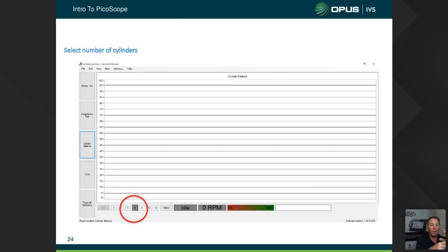And then we can chuck a bit of weight on it, and we move the weight around the prop shaft to different locations to minimize that vibration. It's very, very clever that it can do that. And the fact you don't have to pull the prop shaft out of the car and send it away to an engineering company to balance it up is very clever. But we're not going into that today. There'll be a specialist course we'll run in the future.